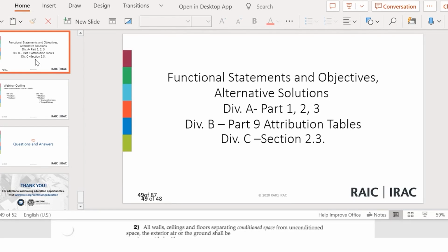So structural design also has limitations. You've got the option of using Part 4, with the loads and specifications in Part 4, or you use the specifications and the span tables in Part 9. So it's a combination. The building codes work harmoniously between Volume 1 and Volume 2. You don't use Part 9 independently of Volume 1 and the rest of the parts in the building code.